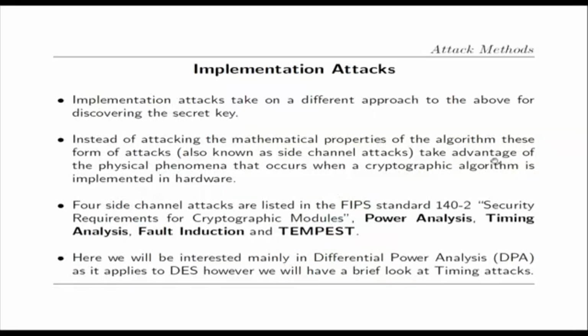So we take advantage of physical phenomena that occur when a cryptographic algorithm is implemented in hardware or software. This is called side channel attack, as if somebody is sitting at the side of the computer or machine where these physical phenomena are being observed. That is why it is called side channel attack. Somebody is sitting at the side and observing the power consumption, power fluctuation, or the time delay.